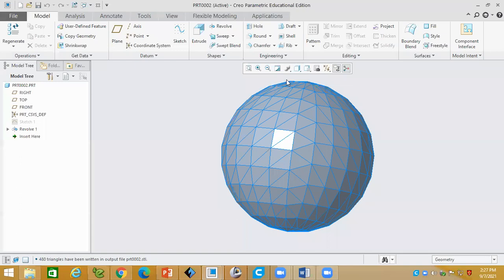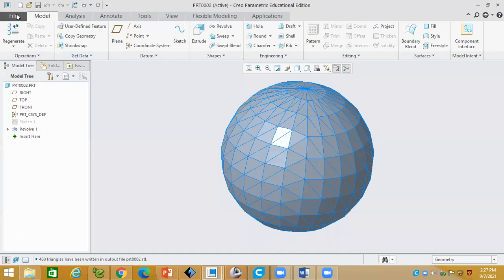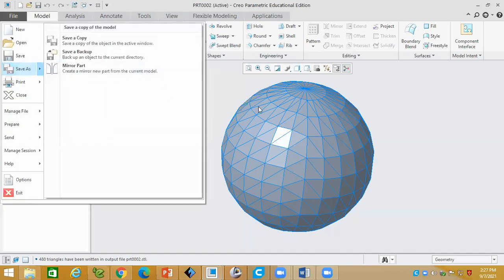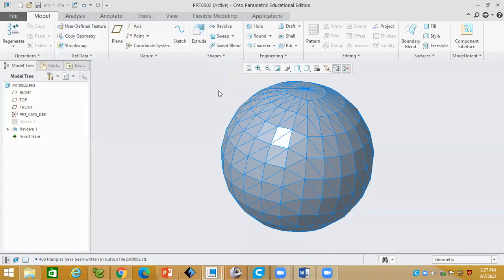Now you can see the outer mesh shape. Now I want to change some of these parameters. I want to make a smoother file. Some conversion parameters are available in CAD modeling software. Here in Creo, chord height and chord angle are there. Similarly, different CAD modeling software has its own parameters to convert CAD data to an STL file. So we have to control the parameters, then we can get an accurate model when the surface is uneven and has curvature.